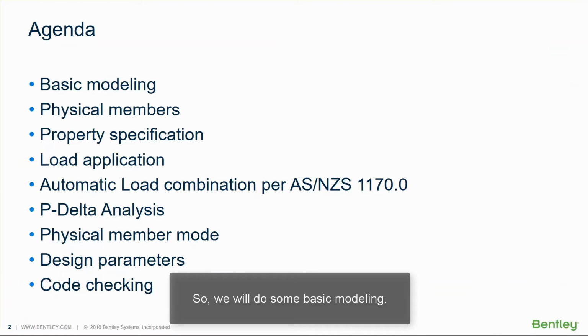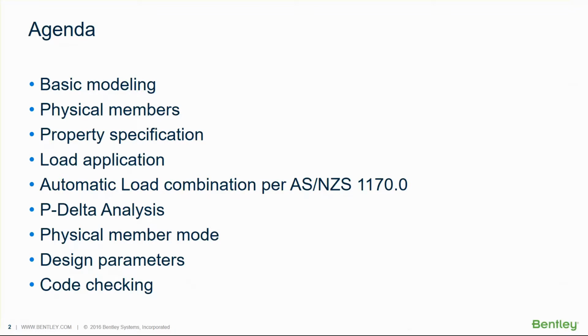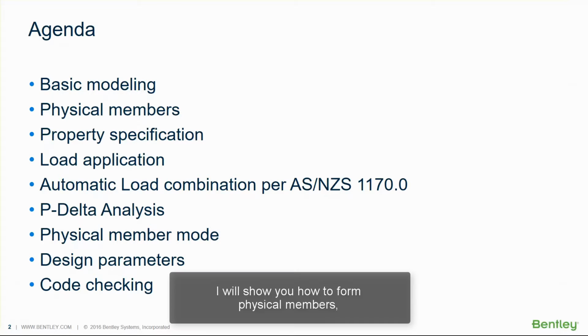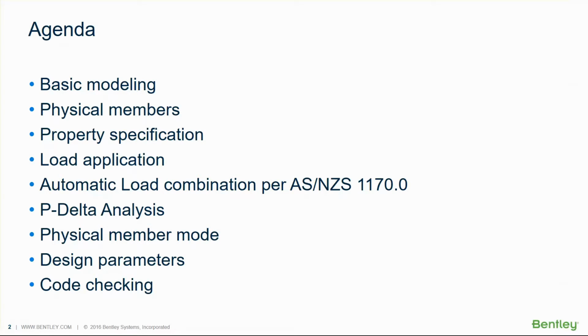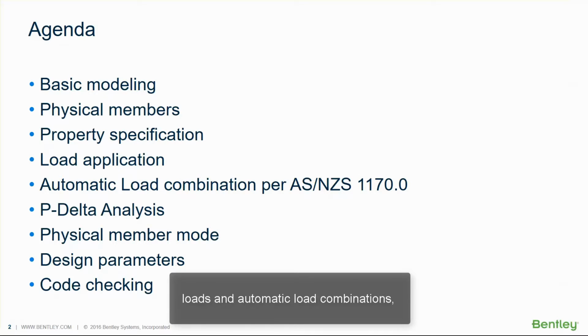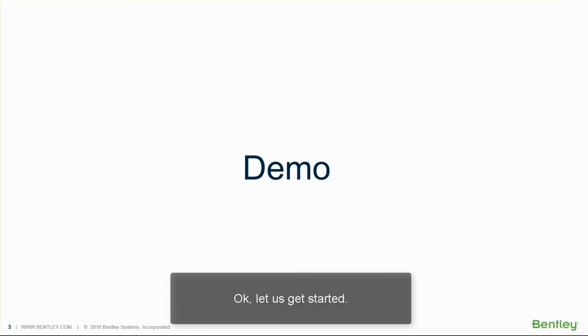So we'll do some basic modeling. I'll show you how to form physical members, how to apply properties, loads and automatic load combinations, P delta analysis, and then specifying some design parameters using the physical member mode, and finally code checking. Okay, let's get started.